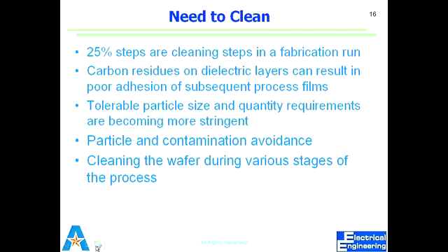We might have done some reaction with an alkaline solution and we want to neutralize it. What are alkaline solutions? pH greater than 7. Basic solution, right? KOH is potassium hydroxide. Potassium is considered a metal. It can degrade the device if it seeps into the substrate. So before I do any high temperature process, I want to neutralize any potassium if it is there on the substrate. So cleaning is not just always cleaning, you have to neutralize some chemicals that might have come in contact with the substrate. It can be carbon left over from polymer from some reactions which happened before. It can be particles, films, or oil. So we clean after almost every major process.